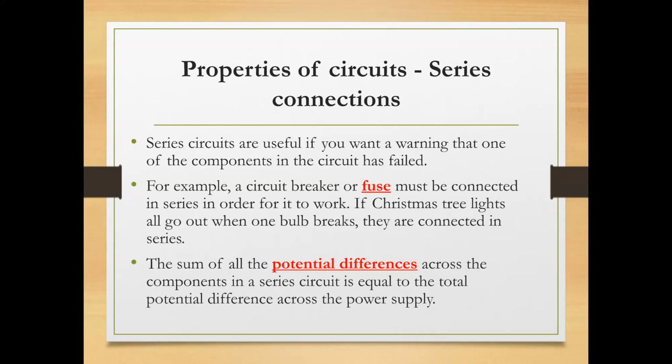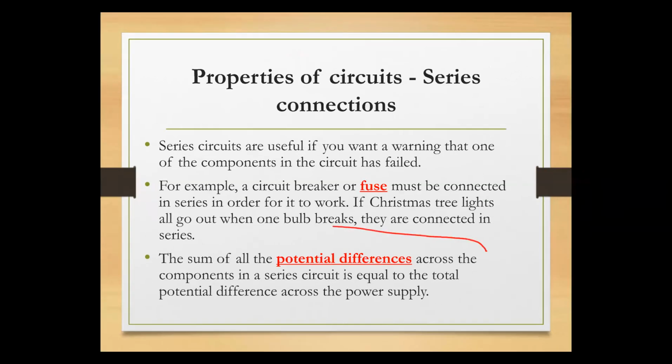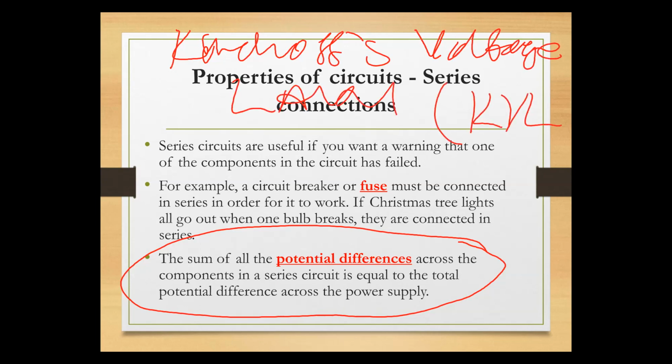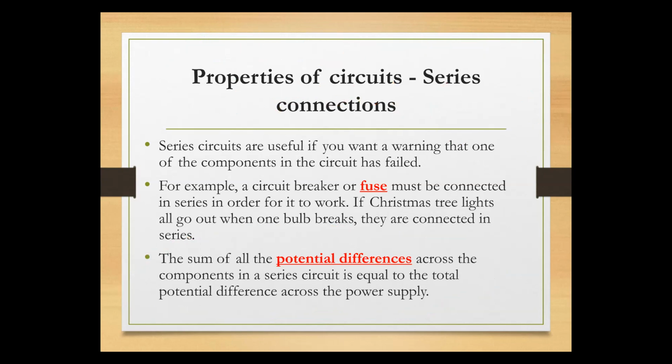Now, in a series circuit, resistance is not the same. In a series circuit, only current is the same, right? Only current is the same. So the rest are different. So now I want to explain this statement. There is a law which talks about this thing. This statement is called Kirchhoff's voltage law, abbreviated KVL.